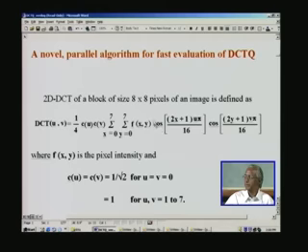So this is a cosine transform that we are applying here, and there are two cosine terms, and this is because we have a 2-dimensional picture, and we need what is called a 2-dimensional DCT for that. Similarly, you also have a 1D DCT, wherein only these two terms will be there, only one sigma will be there, only one constant will be there, and this is the basic definition of DCT, and U is likewise 0 through 7.